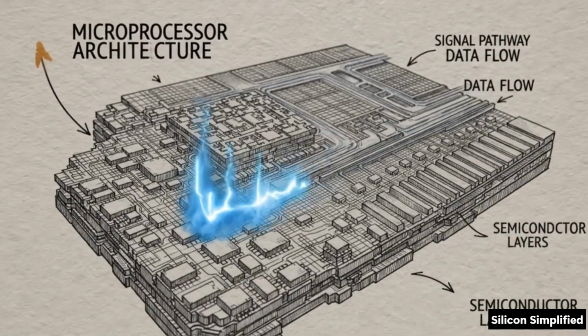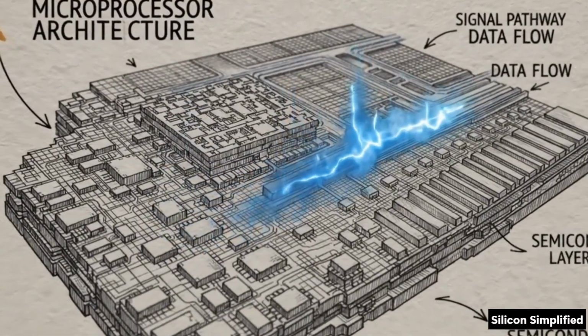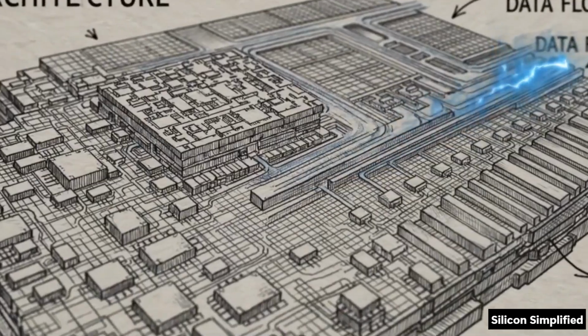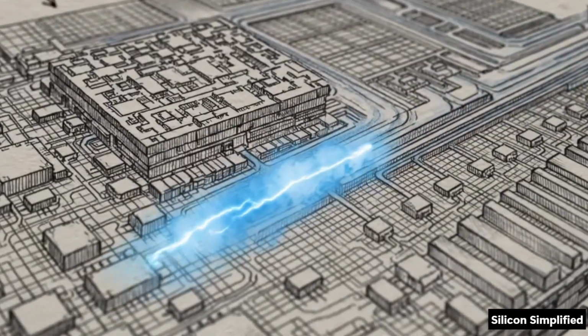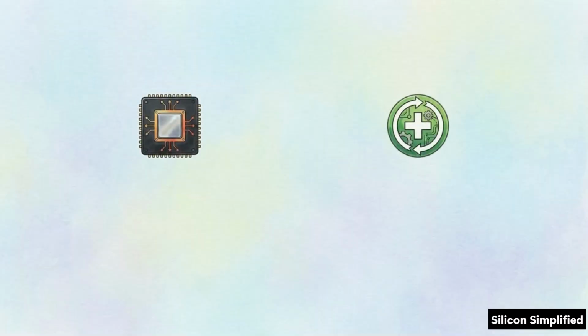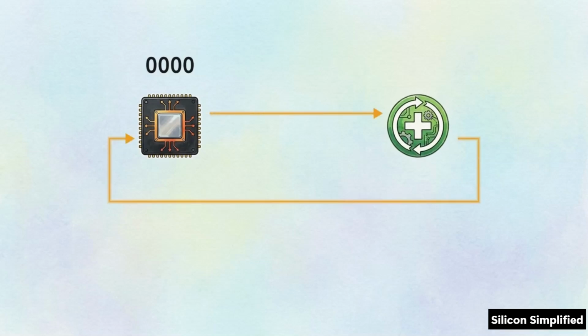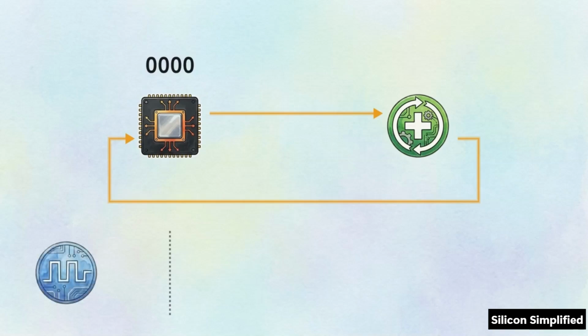At the core of every digital system, the abstract concept of counting must be translated into physical hardware logic. Physically, a digital counter is a sequential circuit built from two distinct elements. First is the state register, which temporarily stores the current numerical value. Second is the combinational incrementer, which calculates the next sequential value based on that current state and feeds it right back to the input. This entire loop is governed by a synchronous clock signal.